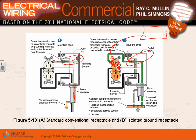Because that conduit is not acting as an antenna, collecting all these noises. Noises are magnetic interference and radio frequencies and whatnot, and dragging it into the grounded conductor and dumping it right across the chassis of your computer. So by doing it this way, that will minimize the interference with your electronic equipment. Your electronic equipment will work better and will not be interfered with.